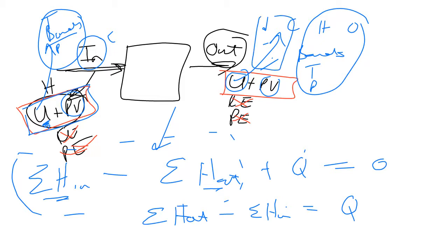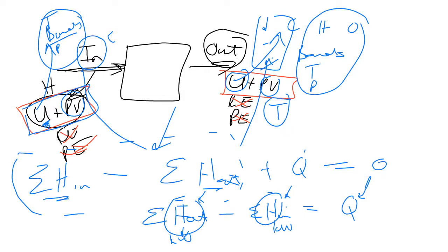Let me go to my database and find the enthalpies of all those components, and in that is built in the change in the bonds. And then you will be able to calculate the kilowatt value of the inlet stream and the kilowatt value of the outlet stream. And that will then be equal to Q if it's a non-adiabatic reactor. So then you would have specified this outlet temperature in Aspen or in DWSIM probably, so that it can calculate the duty of your device, your whatever unit operation.